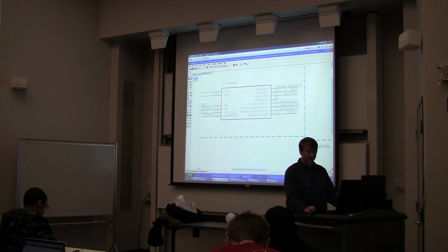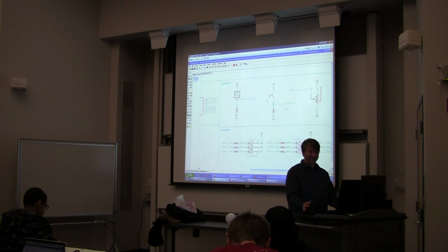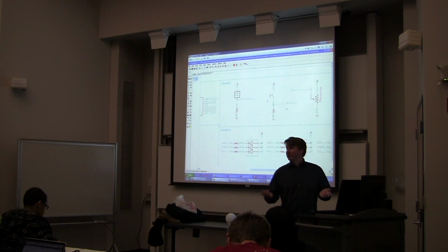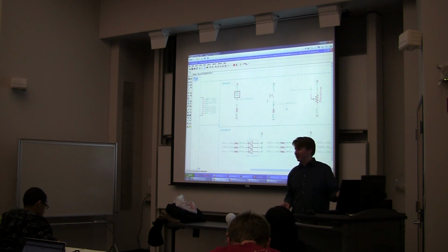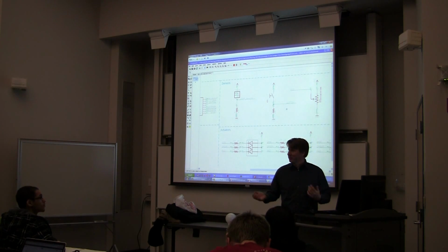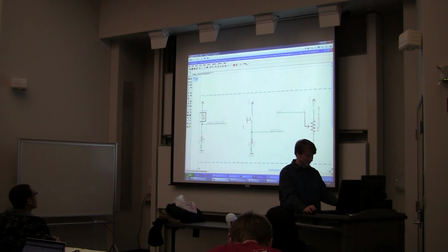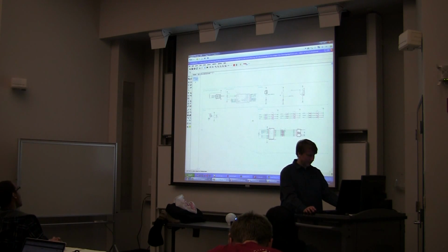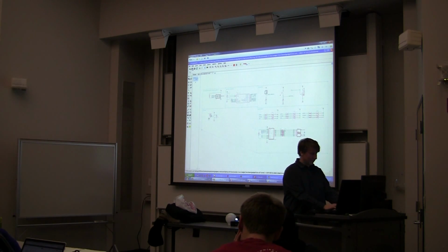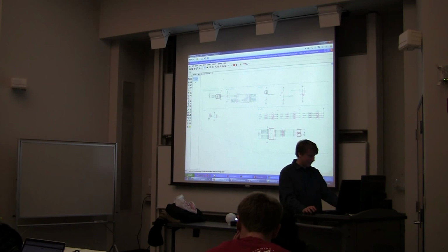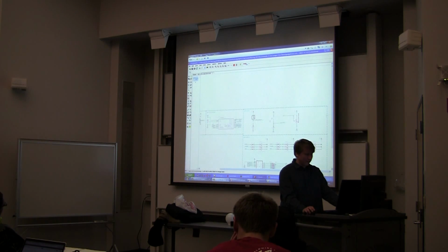Now, if I had gotten way too many and I needed like 2 more pins, maybe that's when I start saying, do I really need a button? Do I really need a potentiometer? Those aren't even in my use case. I just sort of threw those in because I'm bored. So, maybe I don't actually want to do those. Okay, so now that I've got this, my ERC is happy. So then we could look at layout.